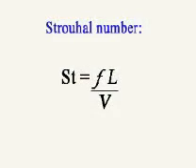Finally, when the Reynolds number reaches values above a few hundred, turbulence begins to dominate the flow pattern. Another dimensionless parameter, the Strouhal number, gives a non-dimensional frequency for such periodic flows. On the other hand, some flows don't change very much over a huge Reynolds number range.